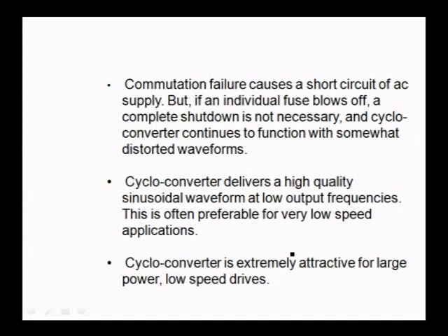This is another advantage. The cycloconverter delivers high quality sinusoidal waveforms at low output frequency. This is very much required for very low speed applications. The waveform is a pure sinusoidal waveform at low output frequencies.